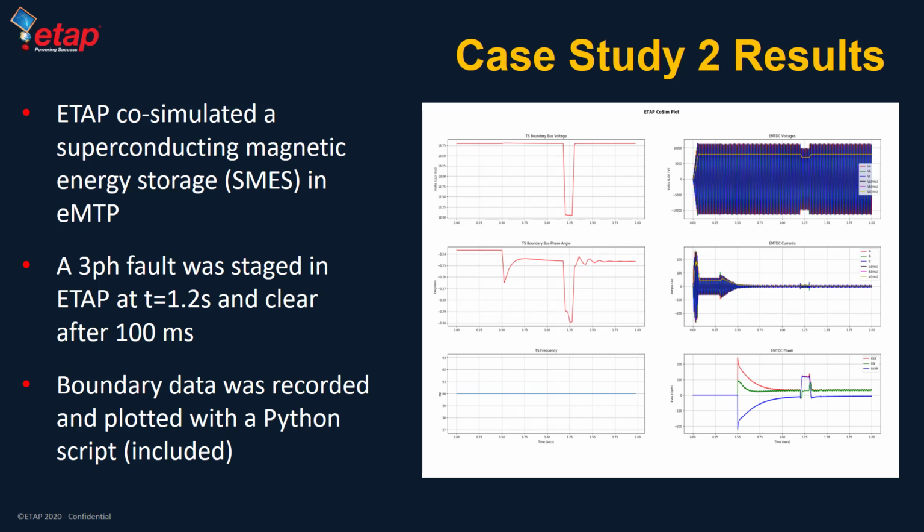That was fast! We showed a detailed energy storage system could be co-simulated with a large network in the Phasor domain. Also, the models in each domain were provided by separate teams. By simply defining the boundary point on each domain, it was possible to have interactive bidirectional flows in the two domains. This is co-simulation by definition.